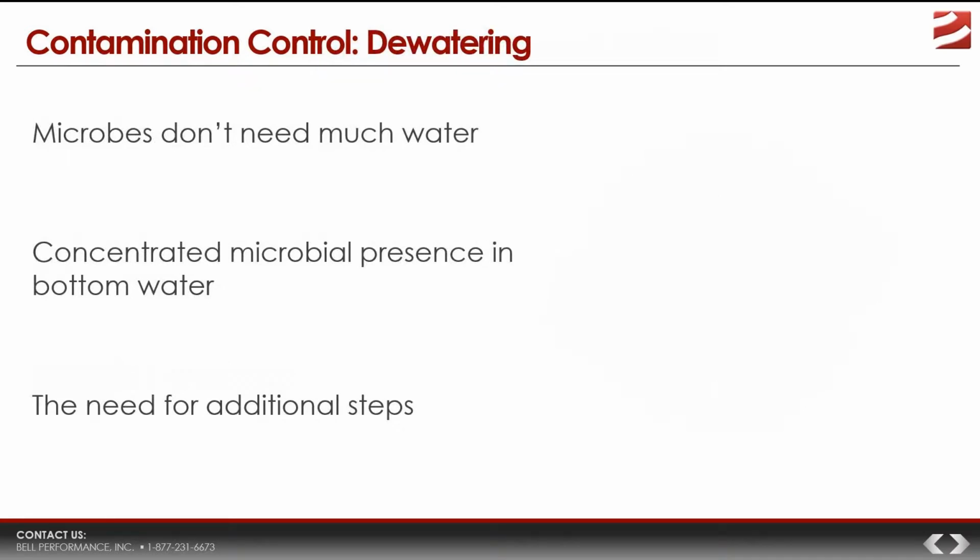Now, on the one hand, we say all the time, microbes need water to grow. We then have discussed that, well, they do need water, but they don't really need much water at all to grow and thrive. Depending on the kind of bulk fuel tank you have, let's say that you had water in it. So you said, okay, we've got to get the water out because we don't want microbes. So you pump out the water, and you get a lot of water out. But let's say you leave 1/8 of an inch in there. Remember that, 2 or 3 millimeters. And depending on the size of your tank, that might be like 2 gallons. So we'll say you leave 2 gallons of water in there.